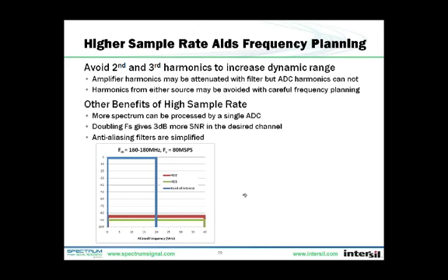If we were to choose to sample that input frequency at 80 megasamples, or about 4 times the bandwidth, as shown in this plot, HD2 and HD3 both alias into our 20 megahertz channel. You can see that here with the red and green covering the blue channel.